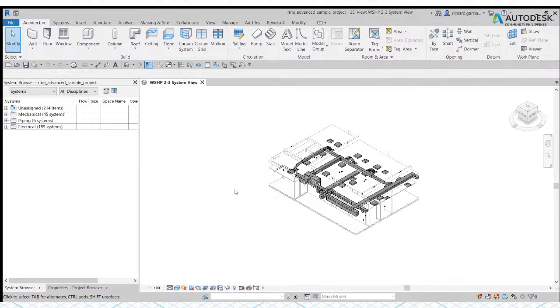When you open a file that is a lower version, Revit will convert that file into your current version. So if you are using Revit 2021 and you are opening 2020, Revit will convert that 2020 to 2021 if you are going to save the file. That's why it's better to use Save As. In case you encounter that, just Save As the file so that you will not override the old file. Okay, is that clear?